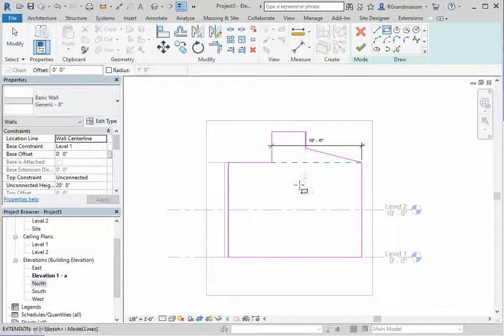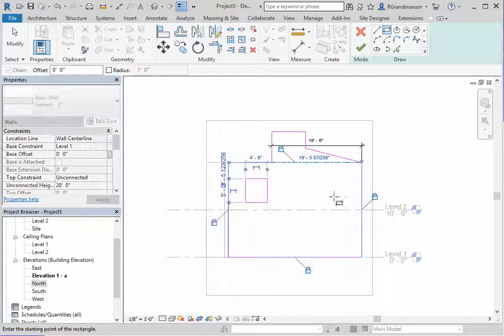I can also then pick other tools and use the drawing tools that you see up here to use different methods for drawing different geometry. And you can also see values in here. So if you want something very specifically to be set to a specific value, you could type in a distance of 5, say for 5 feet.